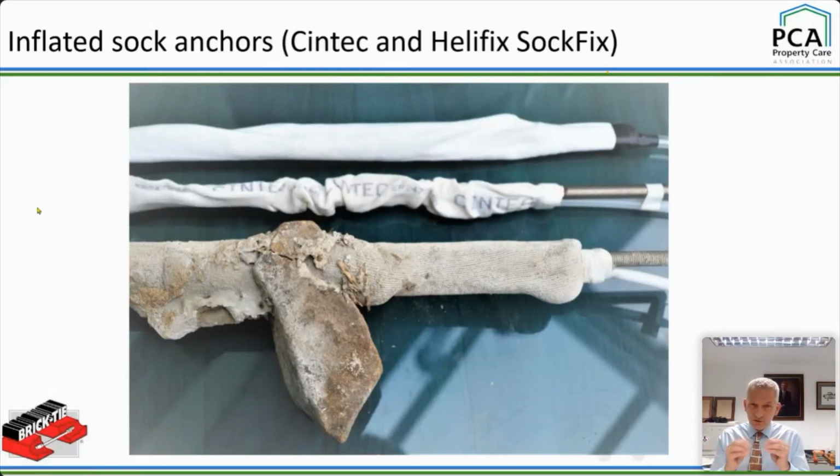You don't want point loads in those weak materials. So here we have these inflated sock anchors. And the thing with inflated sock anchors is it's a bit misleading, because people will think, oh, big, chunky, massive, strong anchors. And they are. Sometimes we put them in concrete structures and test them to 40, 50 kilonewtons. It's ridiculous. That's in civil engineering. But in Joe Bloggs' semi or cottage, when you're installing something as strong as this, you're installing it to be gentle, right? Not to be gentle on the structure, because by having a bigger diameter hole and a deeper hole, you reduce the stress imposed on the substrate when tension or compression is applied.